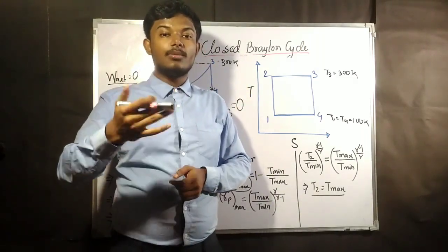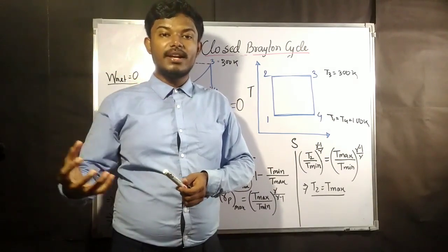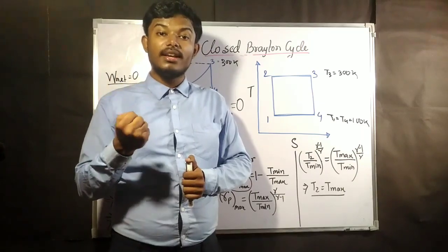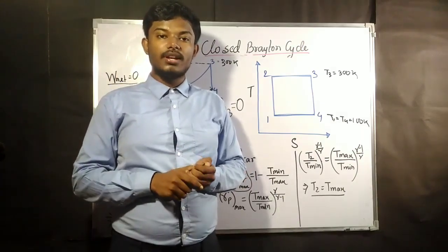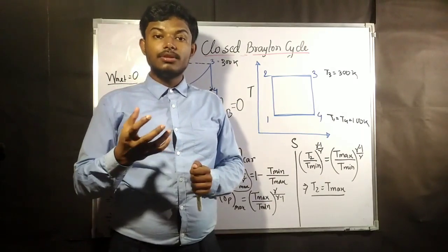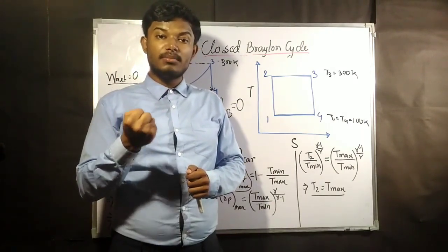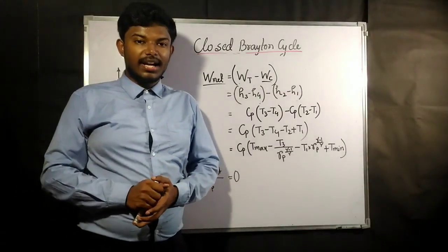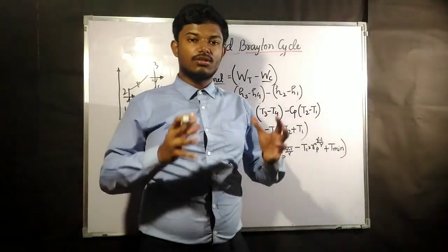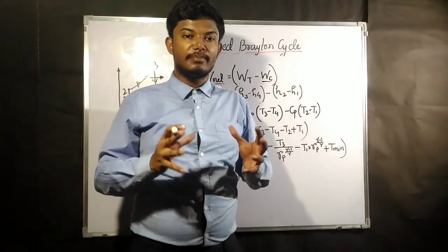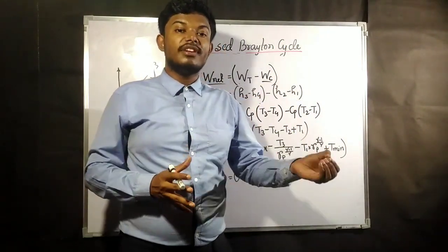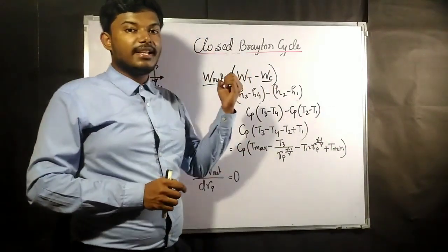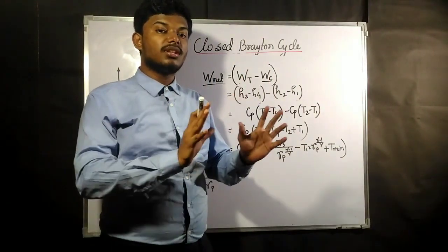So to get the optimum conditions, to make my design better, we are always going to consider the maximum net work output we can get. So in the next board we are going to find the conditions according to the maximum net work. As we have told earlier, to find the optimum conditions in a Brayton cycle, we are not going to give importance to the Brayton cycle efficiency. This we have explained in the last board.